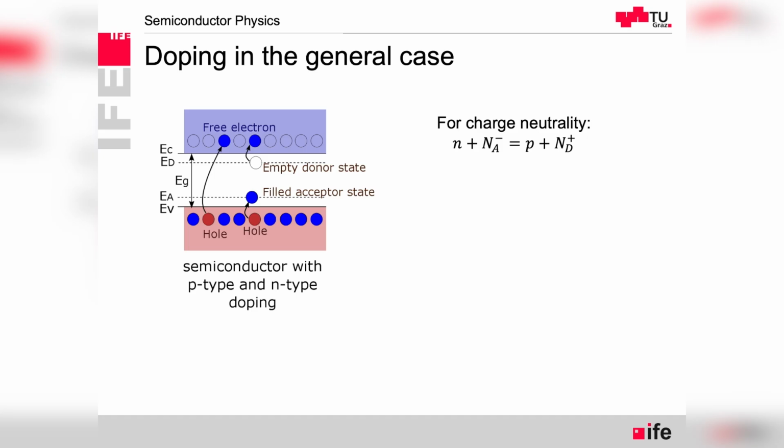And now we're coming back to the typical doping concentration. So as I said, typical range will be 10 to the power of 13 to 18. And that means that if we have 10 to the power of 22 atoms in silicon, we will have one dopant atom per 10 to the power of 4 to 10 to the power of 9 atoms of silicon.